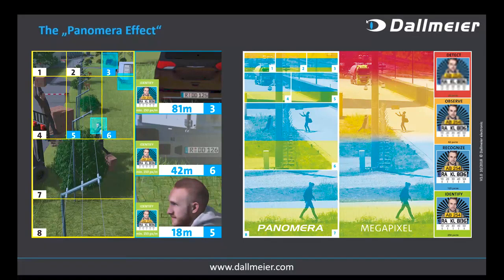Those are the two most relevant for city surveillance, for example, whenever I need to have faces recognized or identified for court use. So 250 pixels per meter or more was, for example, required by the stadia in Russia, or is a typical value that is required in a safe city environment.